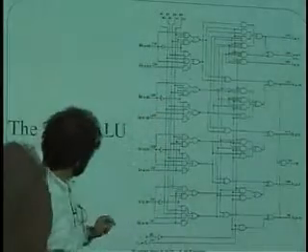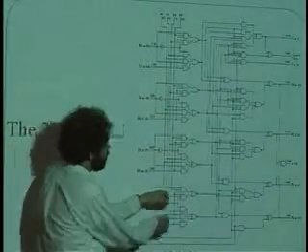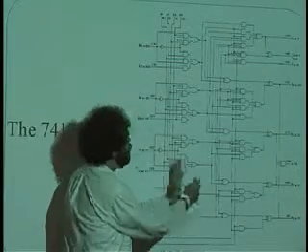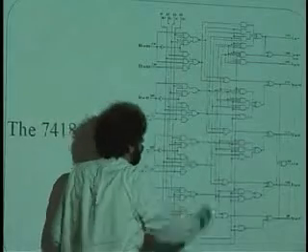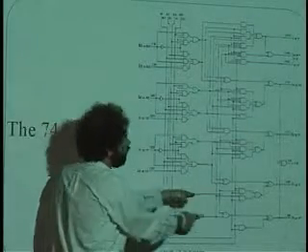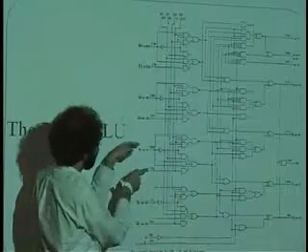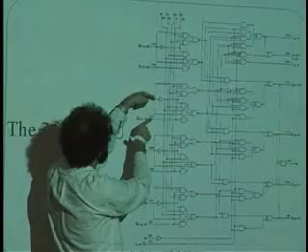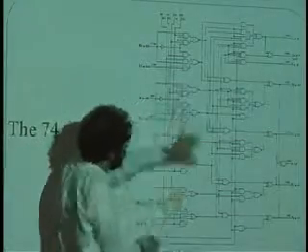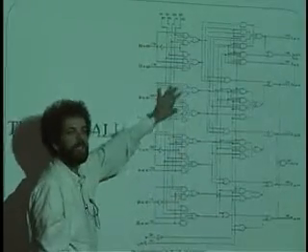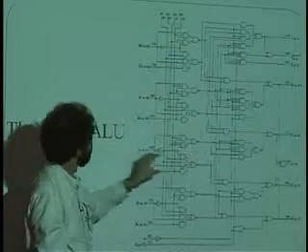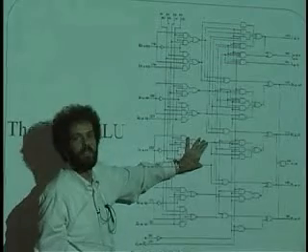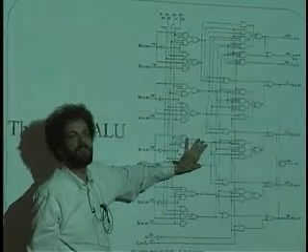And furthermore, whenever we take A and B, we do a little work on them, and guess what? We generate 2 outputs before we feed them to the next stage. There's a line right here where every bit of A and B is recoded to create 2 outputs, and bit 2 of A and B is recoded identically to each stage. Every stage is the same. Guess what the recoding is here between A sub 1, B sub 1, and the mystery wires right here. The mystery wires are G and P.